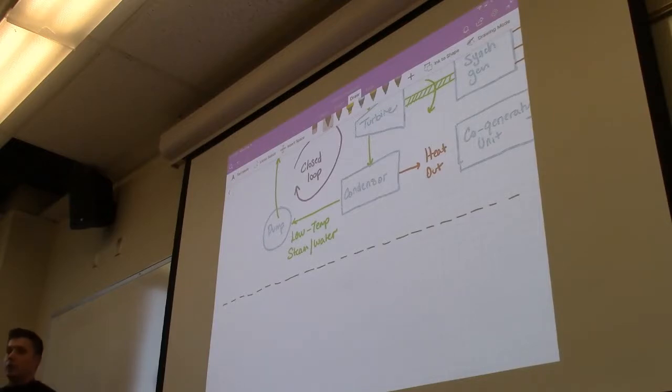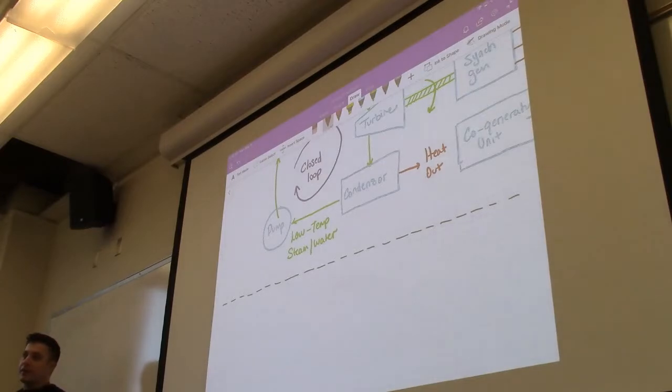Two-pole would be like the example we had where it was just 3 sets of armature windings. If it was a multi-pole machine, then we would have 6, 9, whatever, some multiple of that, which would allow the rotor to turn at a slower speed and generate electricity at the higher frequency, close to 60 hertz.